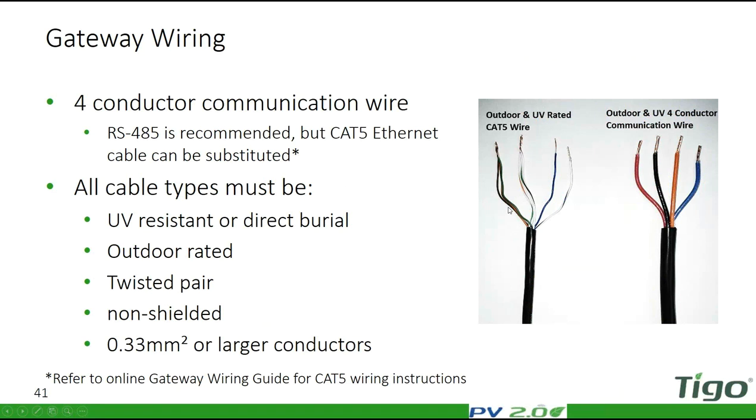The other common cable to use is Cat5. Cat5 cable has 8 little wires. What we recommend is to put them together: three for power, another three for power, plus and minus, and then two that will be used for your communication transfers.